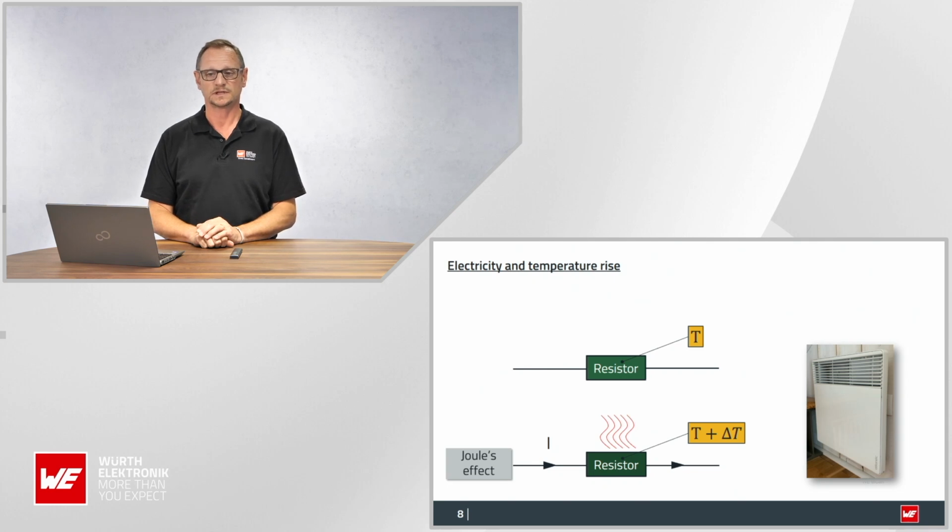This resistor is getting warm, and relative to your ambient temperature, normally room temperature, during operation this kind of connector should not overheat more than 30 degrees plus, following the UL standard. There are other standards out there, like the VDE, for example, but the 30 Kelvin temperature rise is something that we have to look at closely.